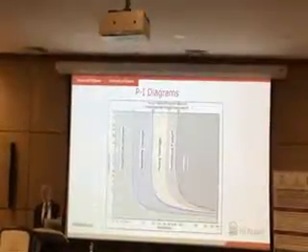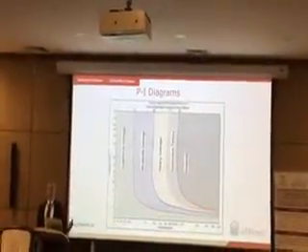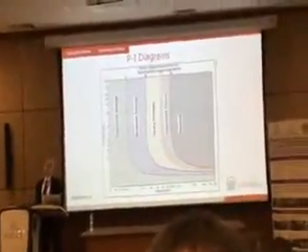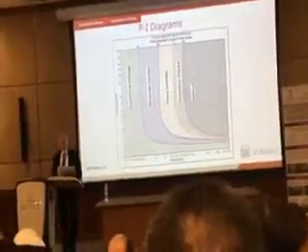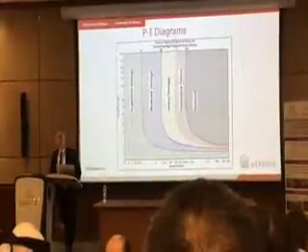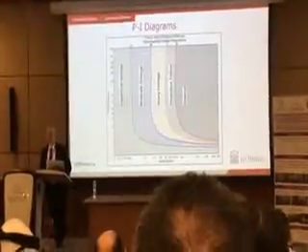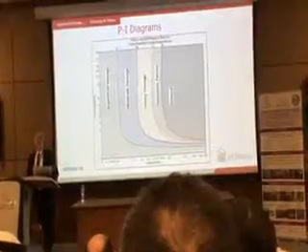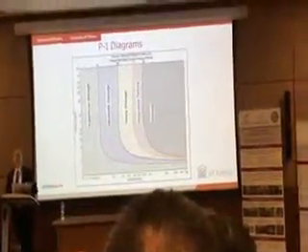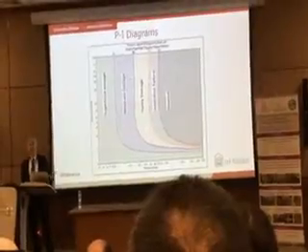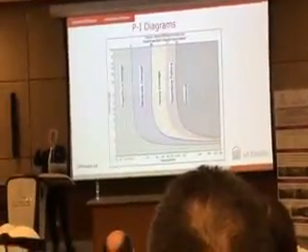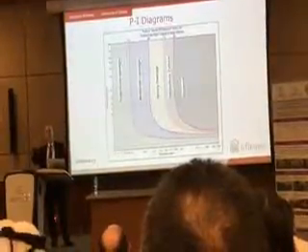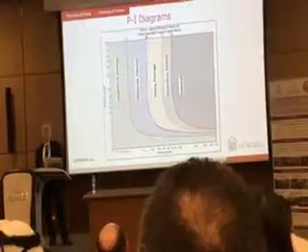So if you're in the business of designing buildings for blast, you will have a whole bunch of PI diagrams available. Once again, my PhD student developed RC Blast, which is a freeware, and it's quite extensively used to develop PI diagrams. But just like column interaction diagrams, you need to have pages and pages of PI diagrams. If you don't want to do any calculation, just enter with pressure and impulse. Impulse is the area under the curve. Wherever the intersection falls, the performance level is accordingly.